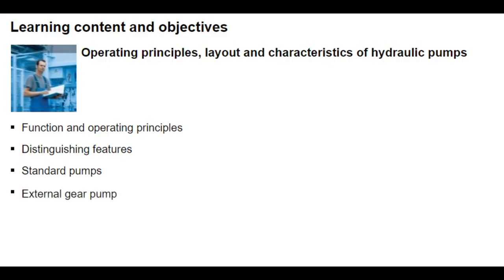As a typical representative of fixed pumps, you should be able to explain the layout, function, and features of external gear pumps. As a typical representative of variable pumps, you should be able to explain the layout, function, and features of bent axis and swash plate pumps. You should be able to calculate pump flow and hydraulic pump power. You should be able to define and differentiate between volumetric and mechanical efficiency, as well as total efficiency, and sketch their qualitative progressions as a function of load pressure.